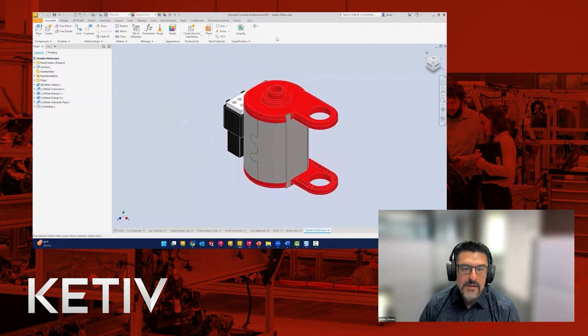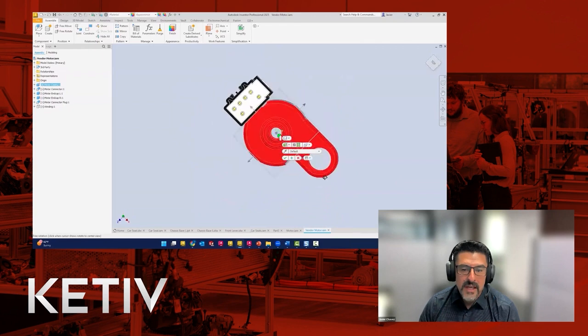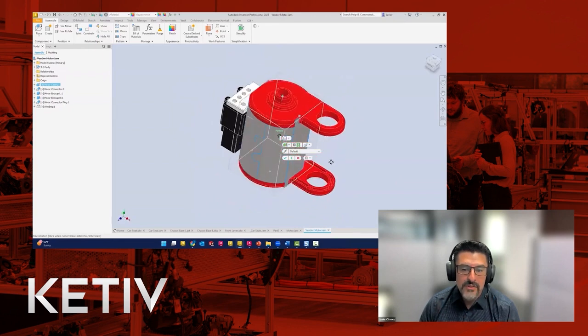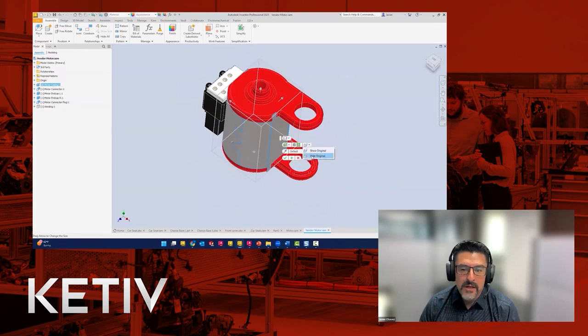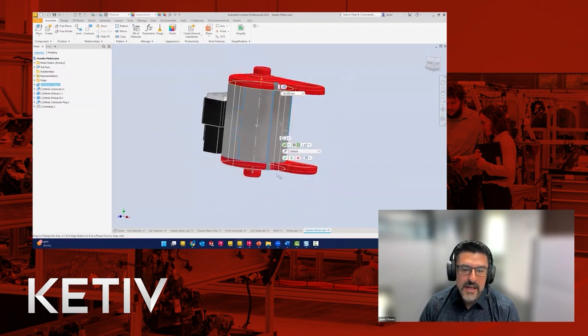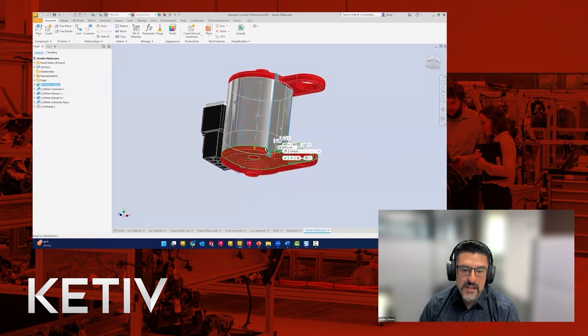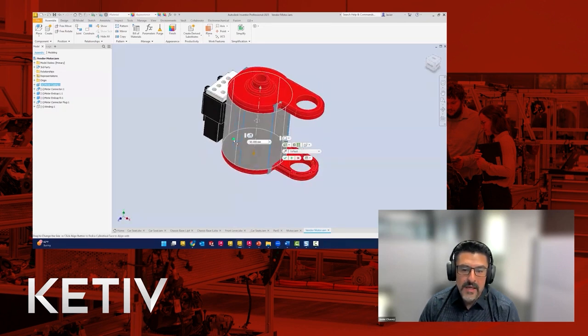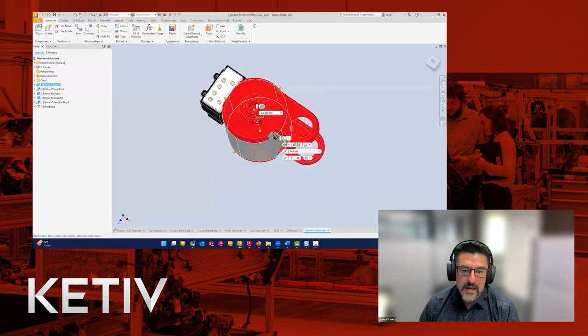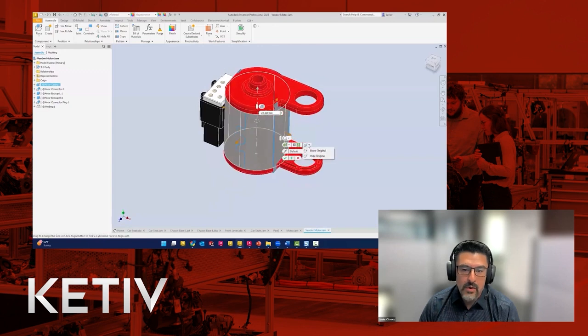The next step is defining envelopes. So we're creating a representation of the casing there, that gray casing, and you have 2 choices, a box. I don't want to represent it with a box. What's closer is a cylinder. So the option to convert that to a cylinder at some point is available. So you're going to see here, okay, that's better. You have tools to size that and snap it to the original casing so that it's the exact same diameter. And you could size it accordingly. So great, now I have a cylinder, and I could either get rid of the casing now or maintain it.